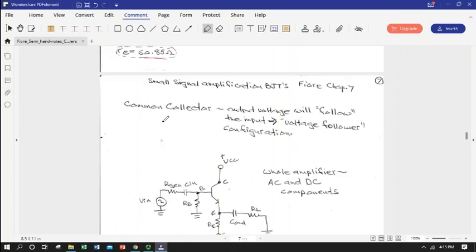But definitely worth working through the examples and really just to lock in your understanding of where your gain is coming from and the ways in which you're defining your input and output impedance. This is definitely a place where it's worth going through the derivations. And again, they all fall out of your AC model, Kirchhoff's voltage law and Ohm's law applications. It's very similar to what we did in defining Q point in the DC model. So back to real simple Ohm's law and KVL expressions are going to serve you to get those numbers.